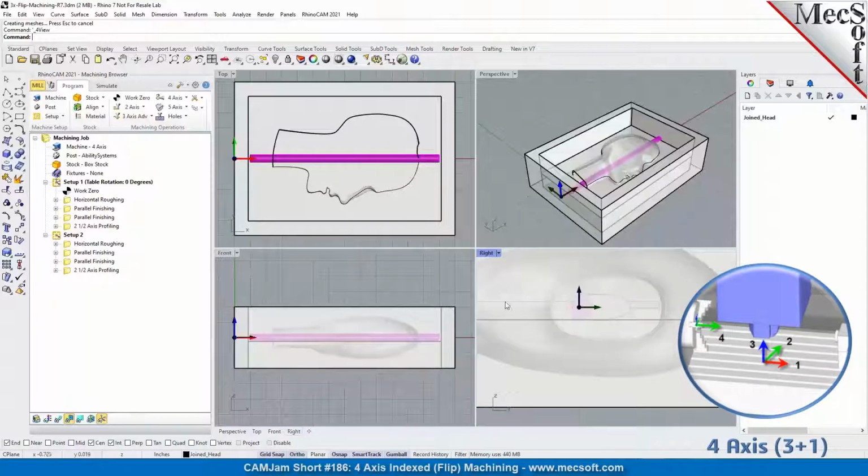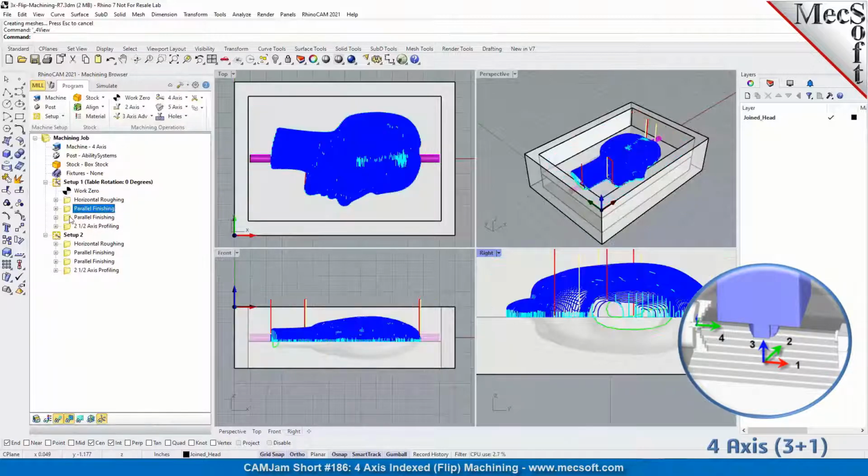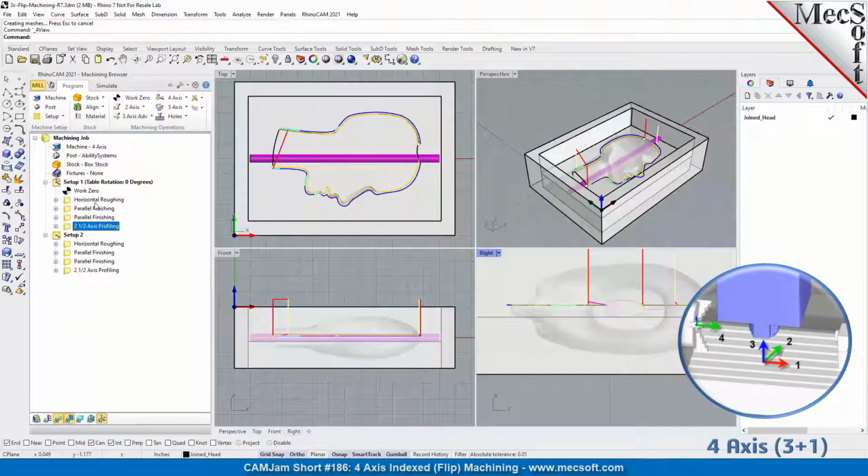So you'll notice that in the first orientation, the catch plane is at the bottom of the cylinder. All of the programs that you initially run are all based on that catch plane. Whenever you copy them to the second orientation, you don't need the catch plane anymore. The programs are already calculated. If you're going to make edits and have side 2 different than side 1, then yes, you may need to move the catch plane to the other end of the cylinder. But typically, if it's a symmetrical part like this, where both sides are identical, then you don't need the catch plane. You only need it in the first orientation because it's already built into the calculations for the second one. I hope that answers the question.